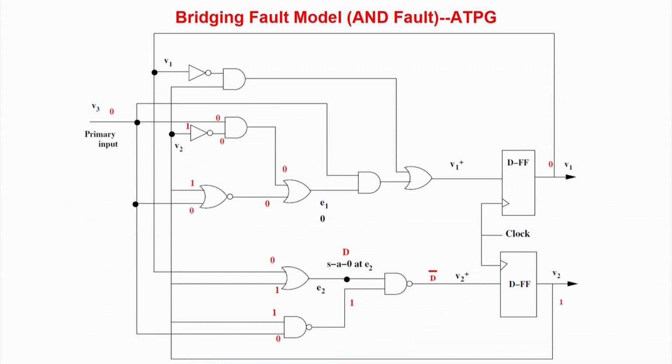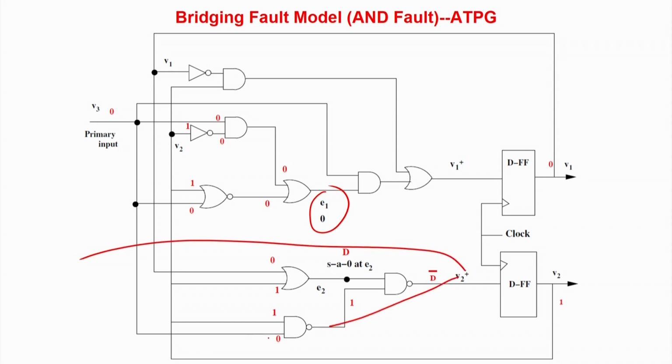So that is why for optimization reasons, again I am repeating, they try to restrict it. But the advantage of this advanced fault model is that if you test the bridging fault, automatically some Stuck-at faults will be tested. Anyway, let us come back. So basically I am going for this level of justification, and then again additionally I should have a 0 over here. So had it been the simple Stuck-at 0 fault, this would have done the job.